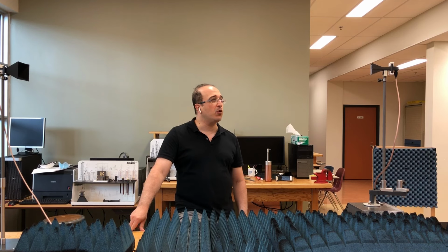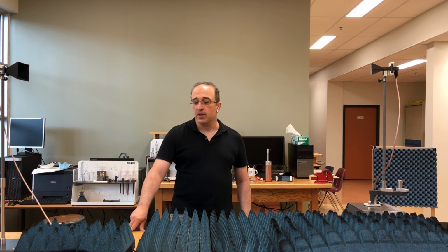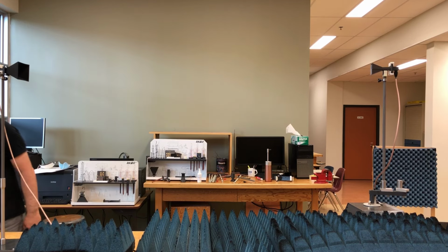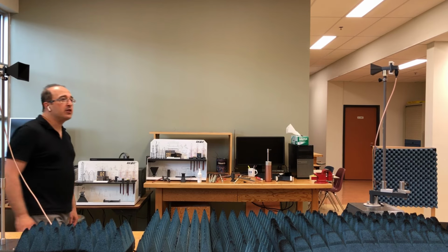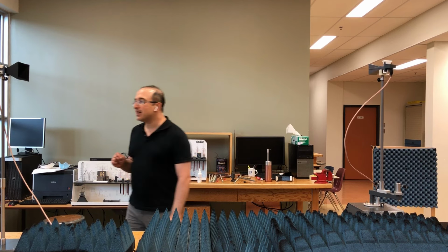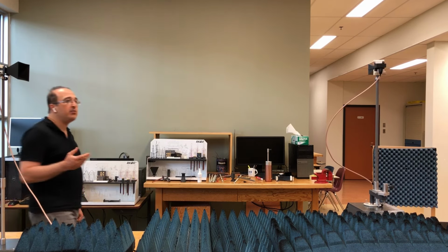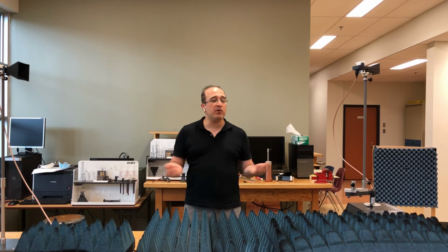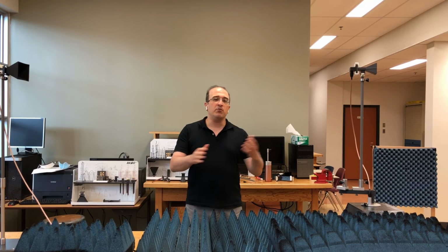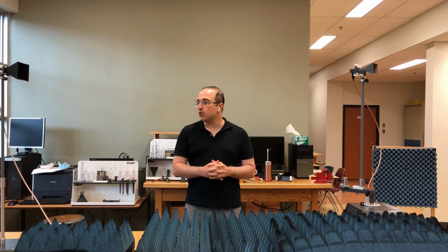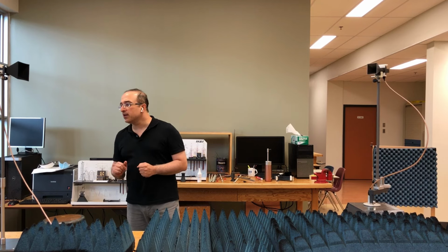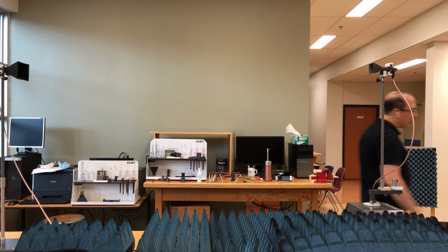So I'm going to perform the measurements and record its H plane. To start the measurement, I'm just going to press start. Something that I'd like to mention is that in the software we currently have 18 dB attenuation, so I'm keeping that 18 dB attenuation as it is. Of course, I shouldn't be here when it's performing the measurement. I usually stand to the side, but I'm just talking. I'm going to measure it again, just for demonstration, and then we'll look at the result. So let's wait for this to finish, and then we can come back and look at our data collection.